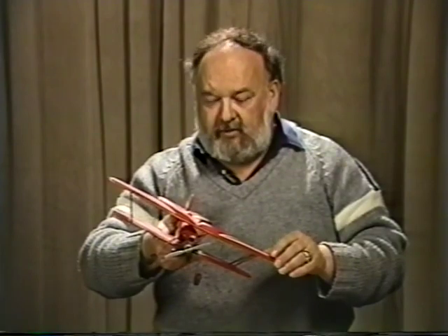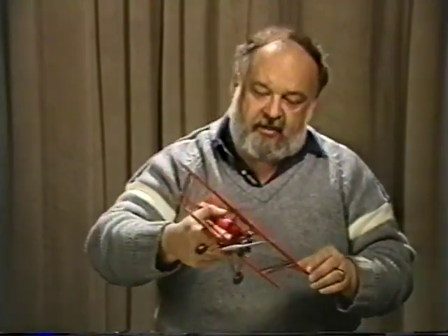Now, if you have a lot of dihedral and you do not have adverse yaw, the airplane would just bank very nicely on you. You can counteract that with roll control, and then using the combination of the rudder and the banked airplane, you can make a reasonably decent turn. But it's not necessary to have a high degree of roll stability anyway. You want a modest amount, you want it to be comfortable, and most of the airplanes today, with, as I was talking about, 4 or 5 degrees low wing, 2 or 3 degrees high wing, will give you a nice characteristic.